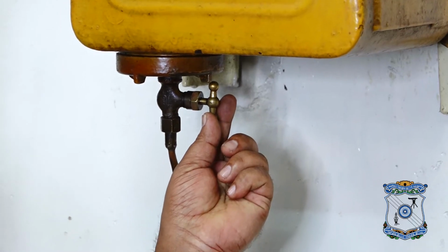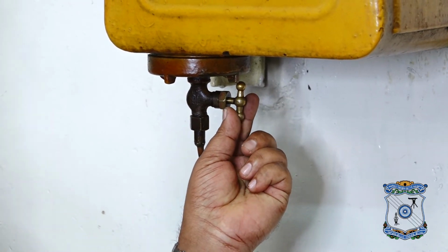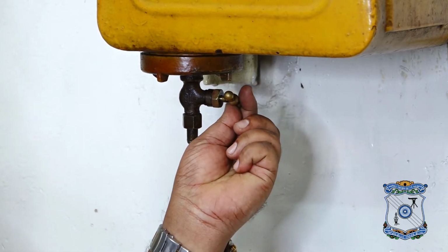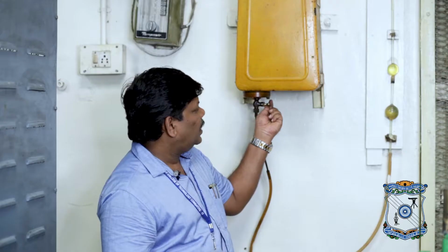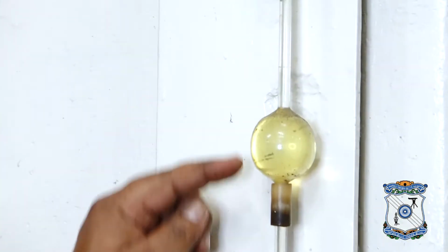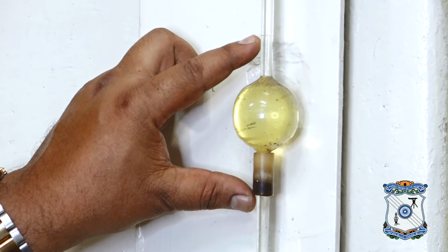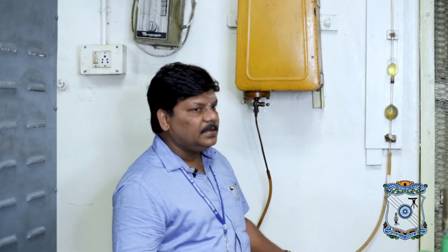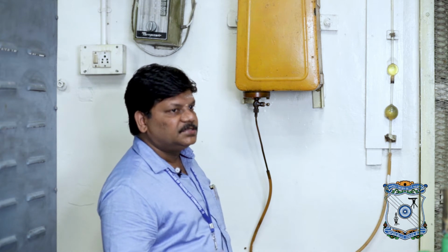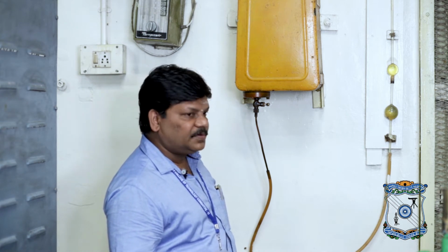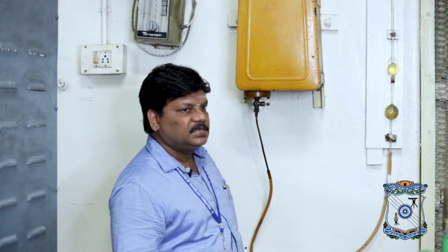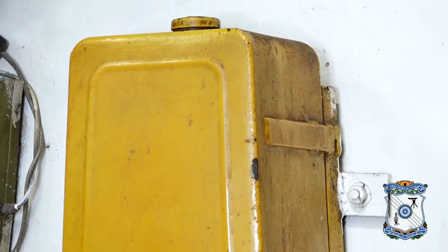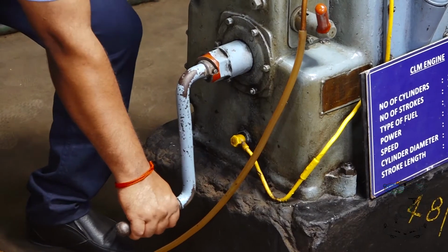After running this engine, once you ensure that the speed is 1500 rpm, you can cut off this fuel supply, and now the fuel will go from this beaker, that is, you can measure this 25 cc of fuel consumption. Thereby you can measure the value of the specific fuel consumption, and from that you can find the best speed where the amount of fuel consumed is less. Now you are going to start the engine.